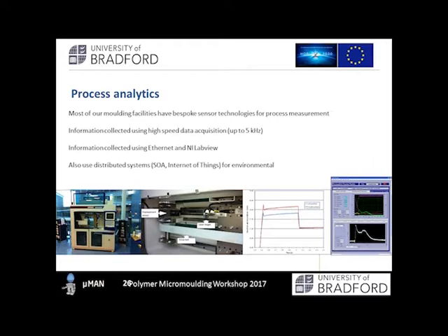of the order of 300 microns, which doesn't sound like a lot from a machine perspective, but when you equate that to an actual volume of material, it can be the entire molded part in error between what your machine is telling you and what we're actually measuring off the system. Now we can correct for it. It's not a big issue.